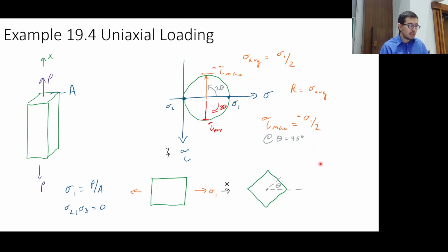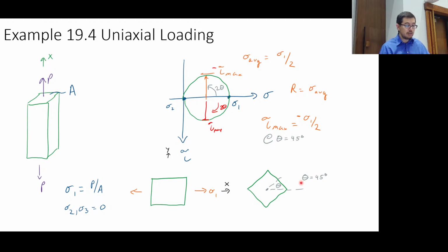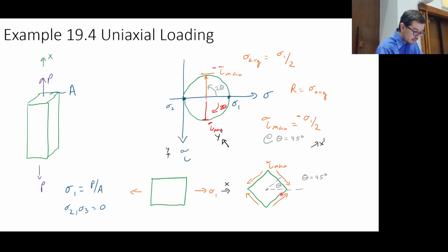So what does that look like? That means if we rotate 45 degrees in this world, we rotate 90 degrees in this world, on Mohr's circle. So in the real world, the material element rotates 45 degrees. On Mohr's circle, it rotates 90 degrees. Okay, and then we can draw that the state of shear stress, x prime, y prime, it's going to be that's backwards. Blast. Okay.